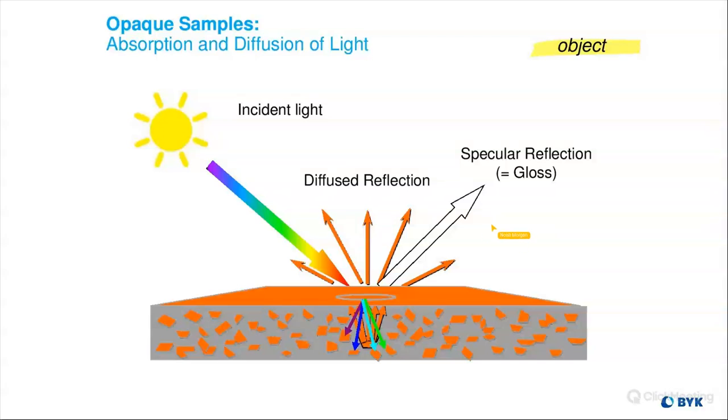Now, if you had a matte surface, something that has a lot of micro texture, it's not going to be glossy, it's going to be very matte. If you look at a matte object at an 85-degree angle, which is a very flat line, it comes down like this, hits the surface and gets reflected back like this. That 85 is going to show you the most reflection for a matte surface, if that makes sense.